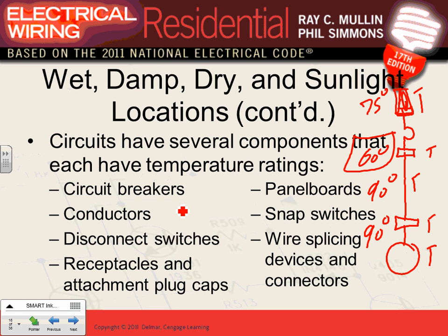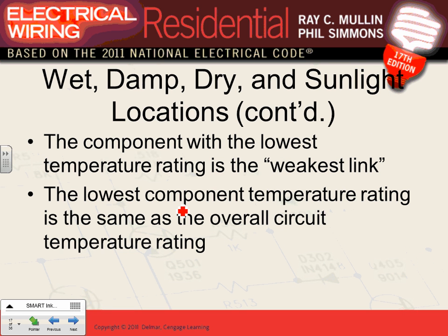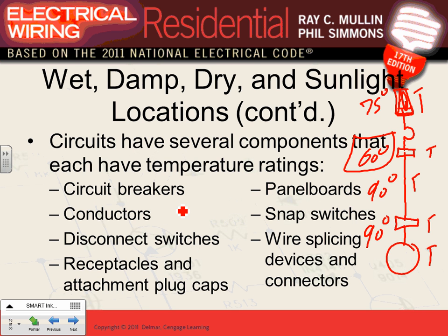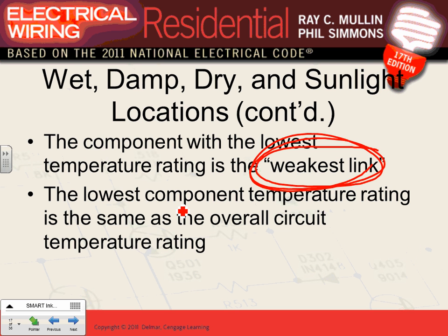If you don't know what the lugs are, you guys remember I wrote yesterday, the divider is 100 amps. 100 or less, 60; more than 100, by default is 75 for lugs. Cables is easy. Based on the installation, THHN will be 90 and so forth. These are all temperature ratings. The weakest link, that's where you always size based on. Always the weakest link in all these temperature ratings. Everybody got that one? You choose the one that has the lowest temperature and you size the amps to be carried based on the weakest link. A lot of you guys don't understand.